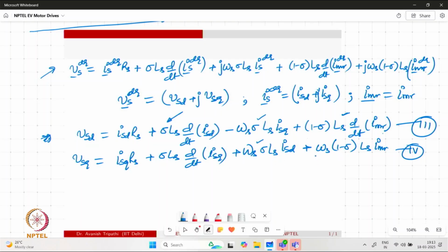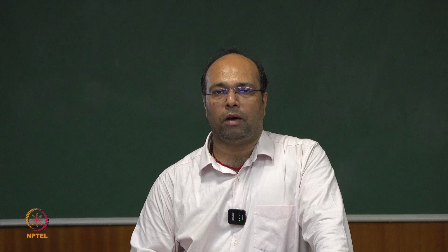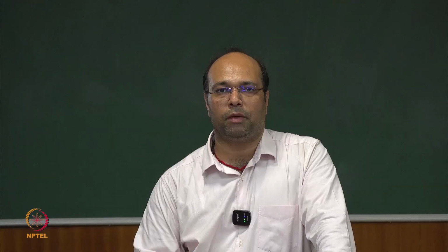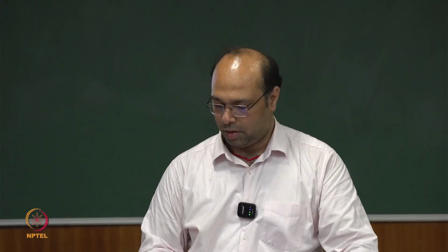However, for the q axis, we have a term which is always non-zero, and it correlates to the back EMF of the PMSM machine that we have seen. So we have a term representing flux and a term representing speed. The combination gives a feeling as if there is a back EMF produced in the induction machine.